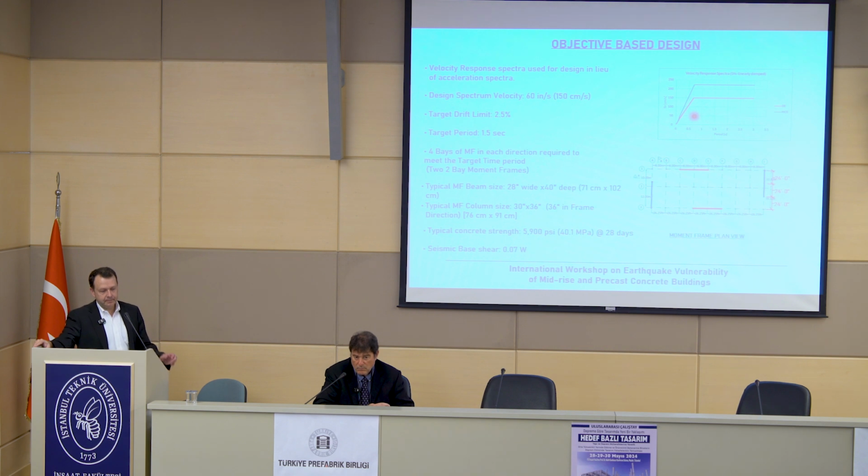In other words, the shear capacity exceeds the moment capacity. We model the expected plastic hinges in the beams as though they're going to go through the rotation, so we deal with them analytically as if they were performing.